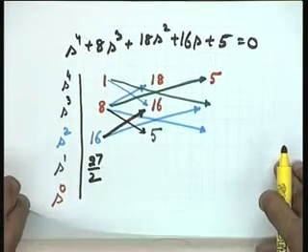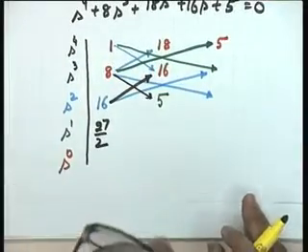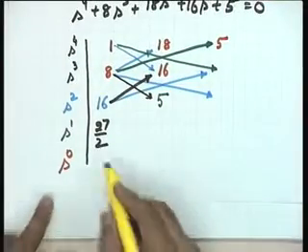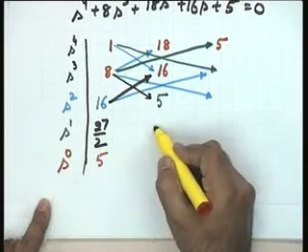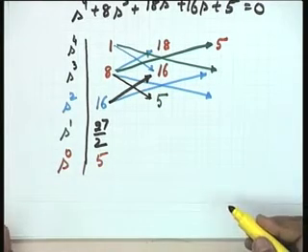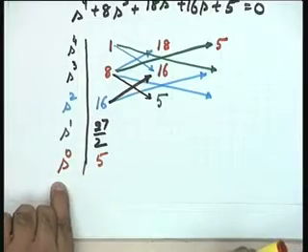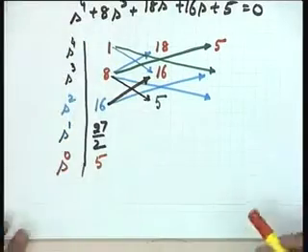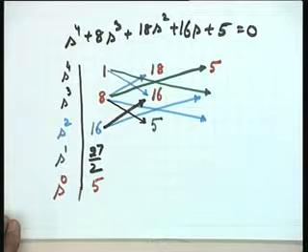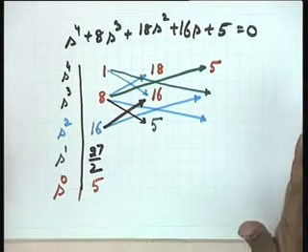Let us go to the last one, the s to the power of 0 coefficient. I think if you have seen the procedure, for s to the power of 0 no calculation need be done. Please help me, what is it? It is 5, because there is a missing term. So this coefficient will get transferred to this place, and hence once you have reached s to the power of 0 by this systematic procedure, you will say that your Routh array formulation is complete. This is the complete Routh array.